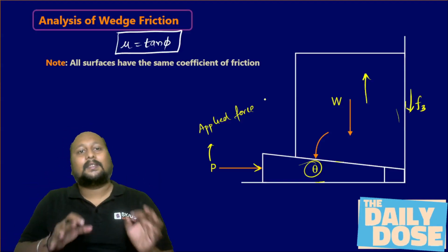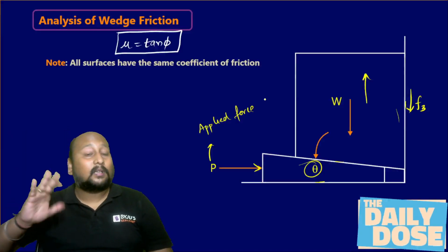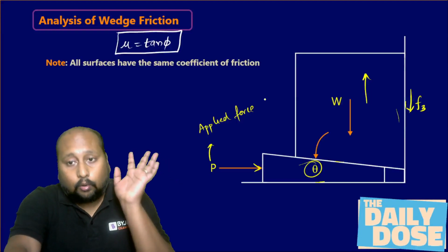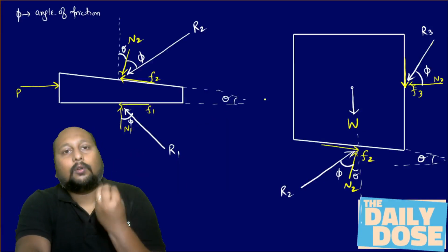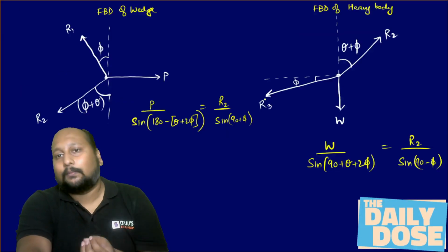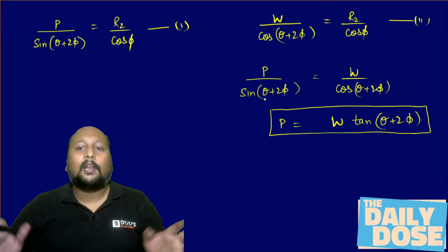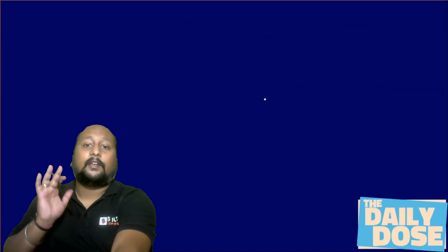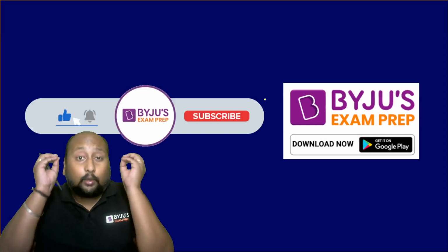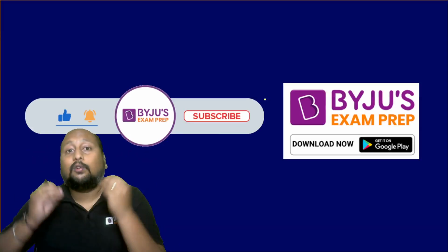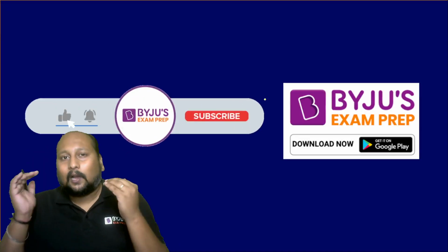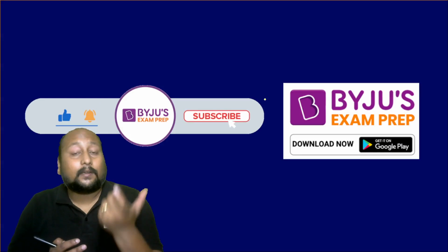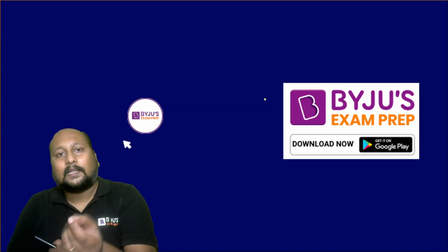That is the reason it's very important not to remember the formulas of wedge friction, but how you need to apply the concept. So this is all about the concept of wedge friction. I hope you all enjoyed and understood how to do the FBD analysis and how easily we use Lami's theorem to do the analysis of wedge friction.